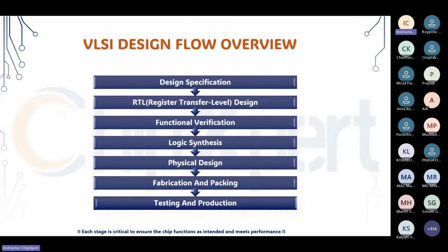So physical design is the stage where you will be physically implementing this logical data on the silicon. How do they physically implement that? Each and every gate is a combination of transistors. Let's say an AND gate is a combination of 4 transistors. Those 4 transistors will be physically implemented. The CMOS design, the CMOS layout that you see, will be really implemented on the silicon. That's how the chip will start functioning.